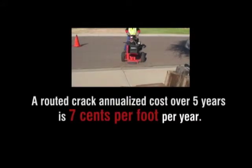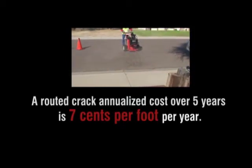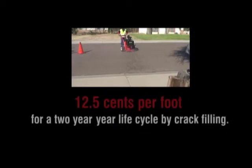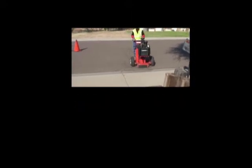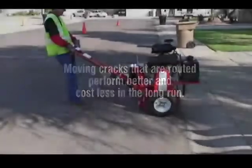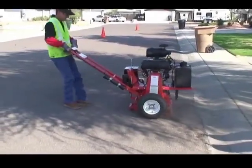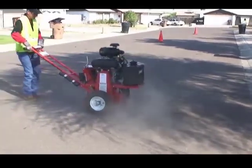A routed crack annualized cost over 5 years life expectancy is only 7 cents per foot per year, as compared to 12.5 cents per foot for a 2-year life cycle by crack filling a moving crack. Do the math. Moving cracks that are routed perform better and cost less in the long run. With the proper training provided by authorized Craftco representatives, routing out a crack is fast, easy, and efficient.